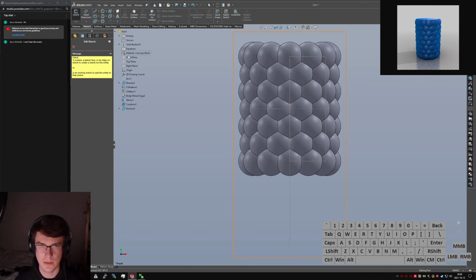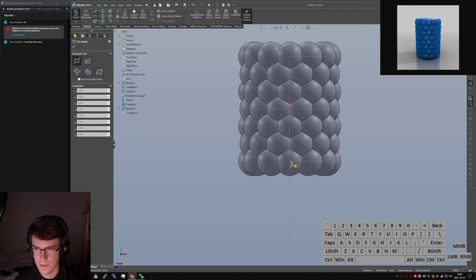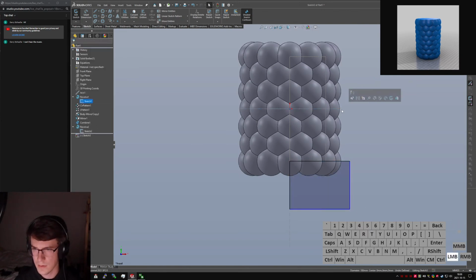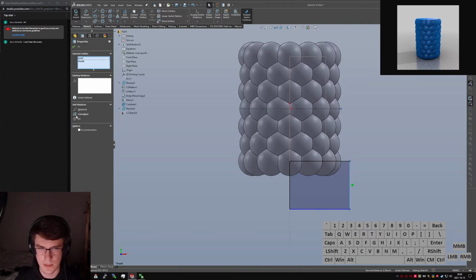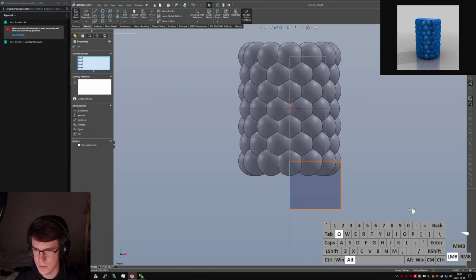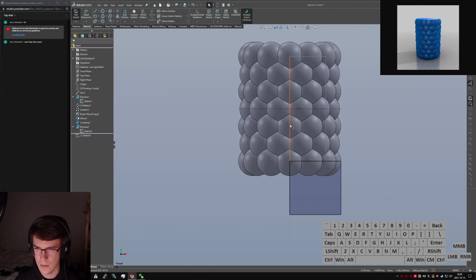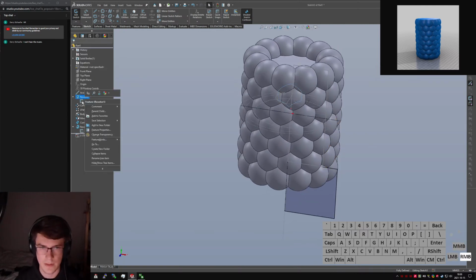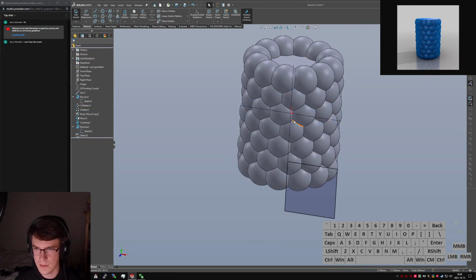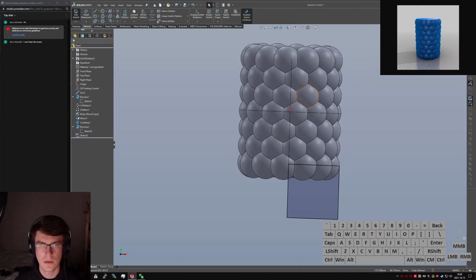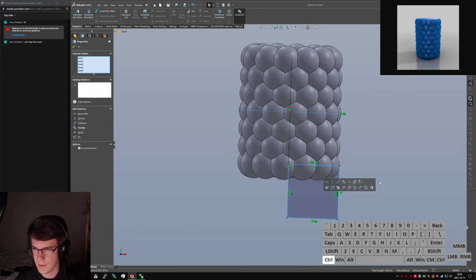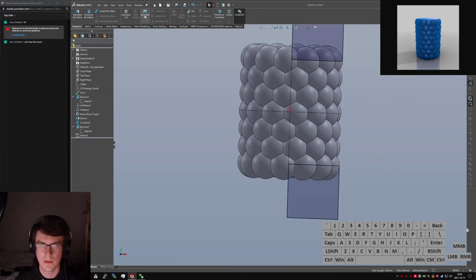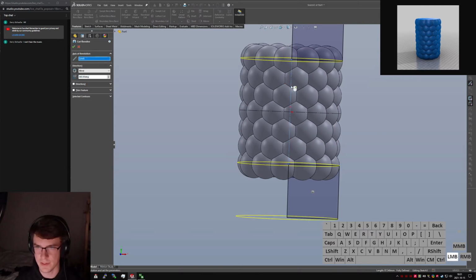Sketch, front plane. Convert that, make it real, pick the endpoint, say coincident, make that a big square, convert that line, make it also construction, hide some other sketches to make sure I'm not doing anything silly. Looks good to me. Features, ooh, click, click, mirror, revolve to cut. Save myself an extra op.